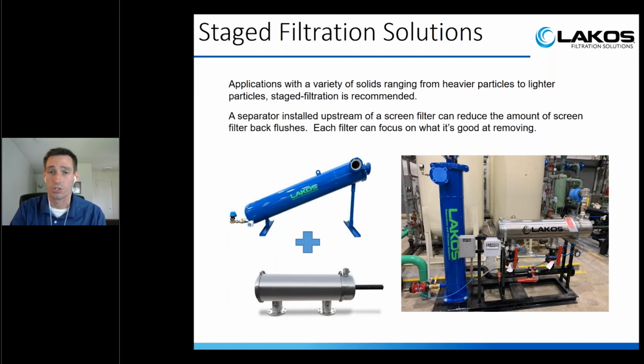So this is a common solution for applications. You may be pulling from a river that may have sand and organics, or whatever application you run into that has a combination of solids that you're dealing with. Stage filtration is a very good solution to solve those problems.